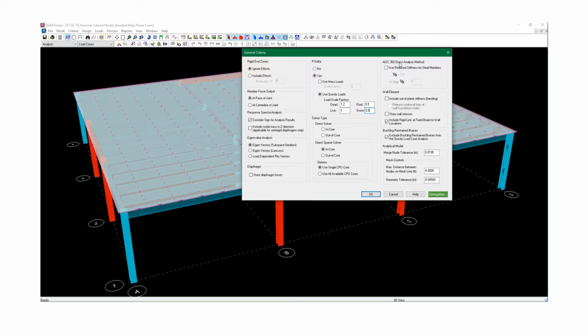Okay, so obviously this is the option to select the use of the direct analysis method. In this case, we will. And to find out what the tau beta value is, if you wanted to use a different value of tau beta, if you knew what it was already, you can do that. But this is an iterative approach in order to determine what tau sub b is, if you will. You first have to run the analysis and then look at the performance of the structure, go into each individual member, and it will give you various tau sub b's.